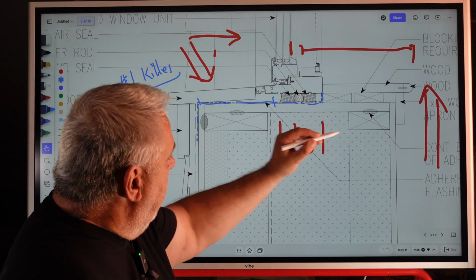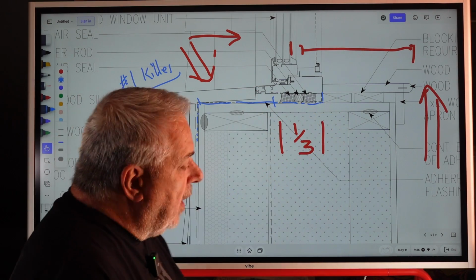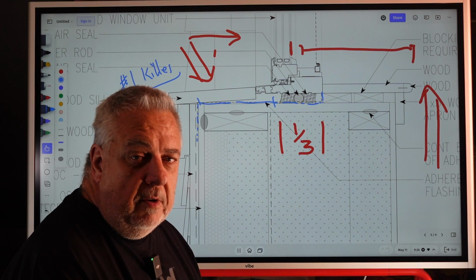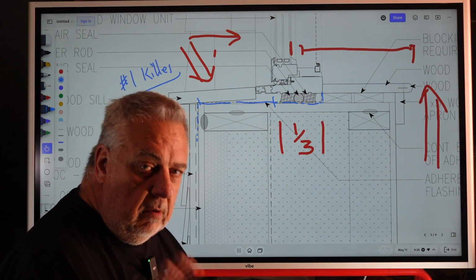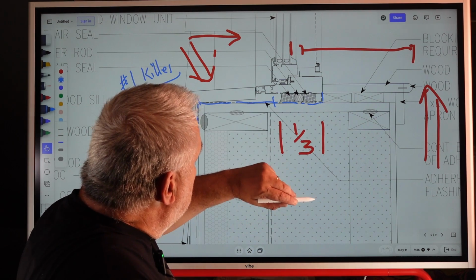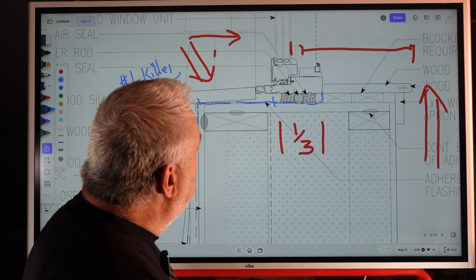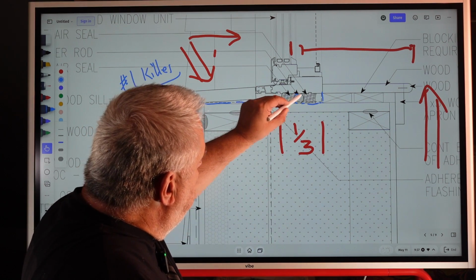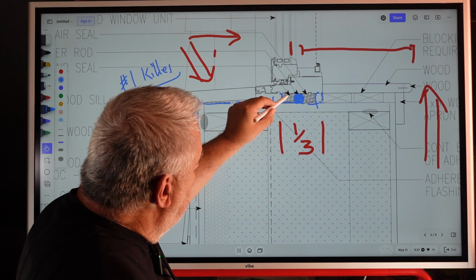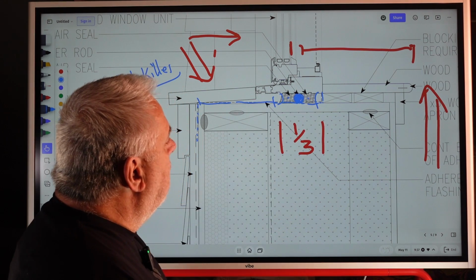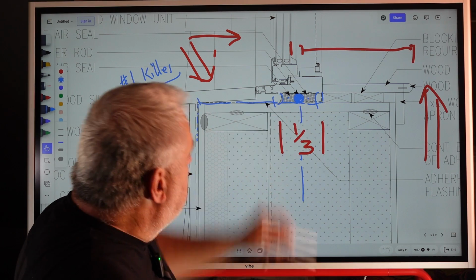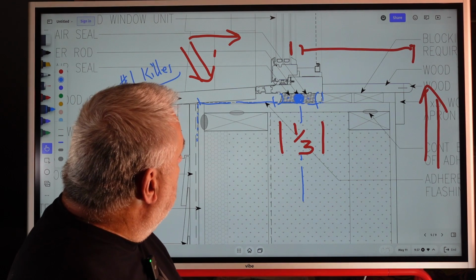But we push the window in. Notice there is no nailing flange on this. These are flangeless windows. I think it was my first experience ever using a flangeless window, so there were some new things to me here. But notice the window got installed, I believe, with some installation clips. But our detail here was pretty much the same. We did a giant backer rod, and then we did some foam sealant on the outside, and you can see it's pretty much almost centered in the wall there.